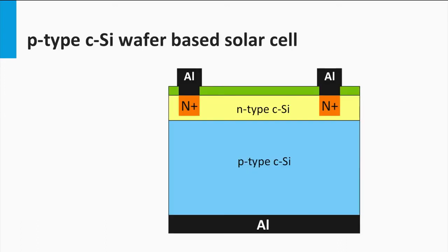At the back surface of the solar cell, we have similar issues playing a role. As the electrons have to be collected in the n-type layer, the holes are collected at the back contact. As electrons are the only charge carriers that exist in a metal, you have to realize that the holes recombine with the electrons at the contact interface. If the distance between the PN interface and the back contact is smaller than the typical diffusion length of the minority electrons, the minority electrons can be lost at the defects at the back contact interface due to Shockley-Read-Hall recombination. How can we reduce this loss mechanism?